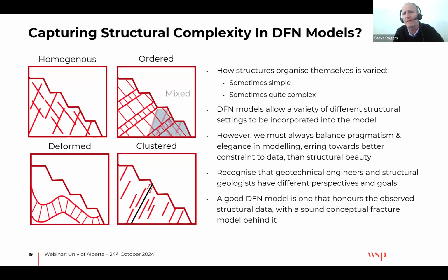when this is applied to engineering, it's really nice to have beautiful models, but sometimes we have to be a little bit more pragmatic. And the geotechnical engineer in charge of a pit slope definitely wants something pragmatic and doesn't necessarily want something that's structurally beautiful, because we've got to trade off validation. We know there's data, rather than geological inference and allowing structures to do things that we believe they do but we don't necessarily see. So, like I said, at the bottom, the message is a good model is one that honors the data, but has a sound structural model behind it.